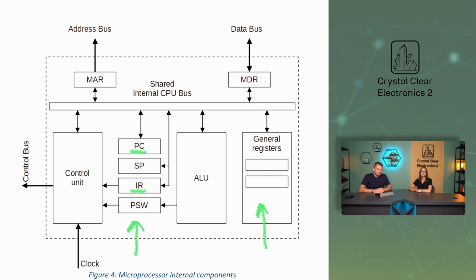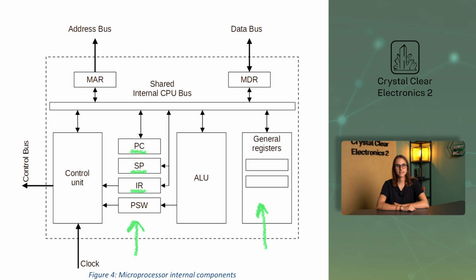The abbreviation SP stands for stack pointer, which is basically a memory address register that points to a specific location in memory. To understand why it exists, we first need to clarify the concept of the stack. The stack is the part of memory that is used by a function when the program is running and in which the function can store its own local variables. The exact position of the processor in this stack during execution is determined by the value of the SP, all of which you will learn more about in Chapter 3.